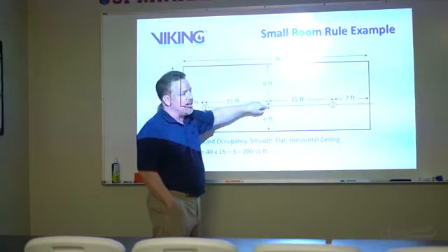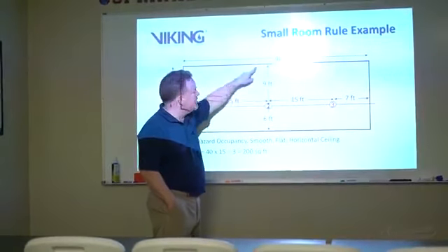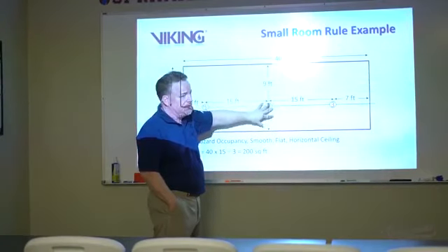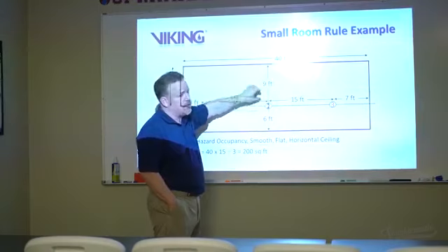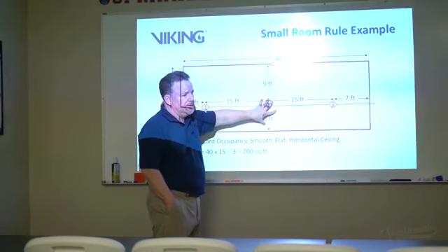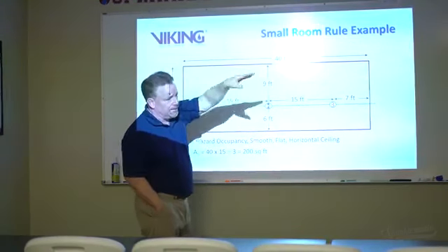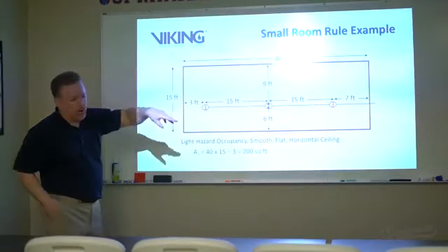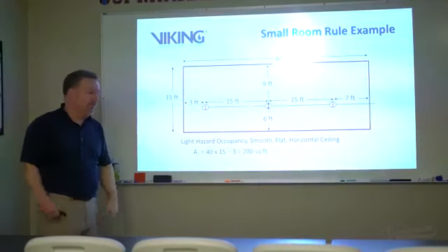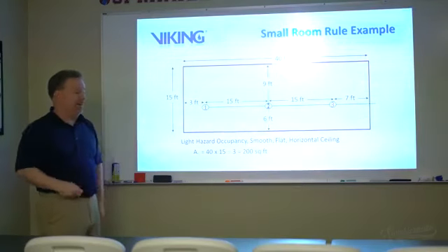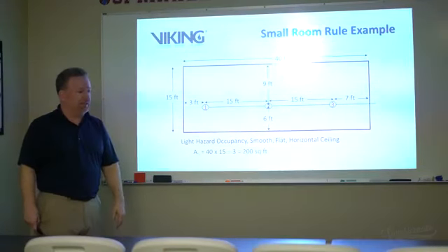It's going to slow it down a little bit. Yeah, because it's not going to respond as quickly. You would have a quick response sprinkler, but it's going to slow it down a little bit. Okay, and that's why we say all the openings except one 3-foot opening has to have a lintel, because we want to collect it up at that level, and not let the heat escape.